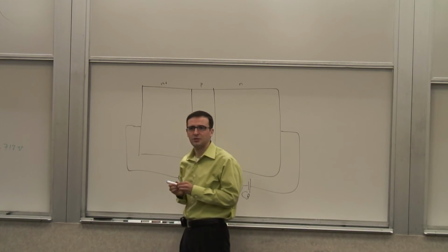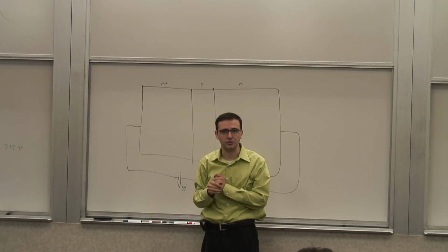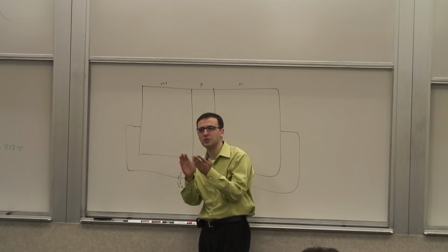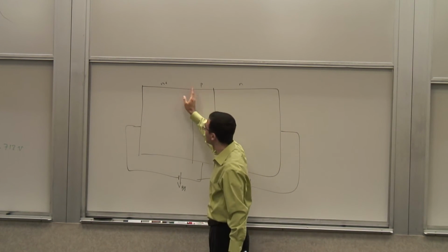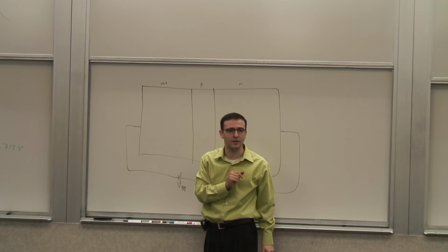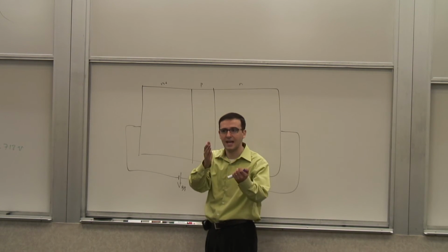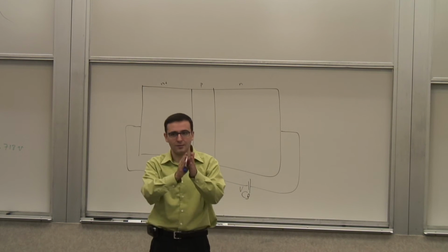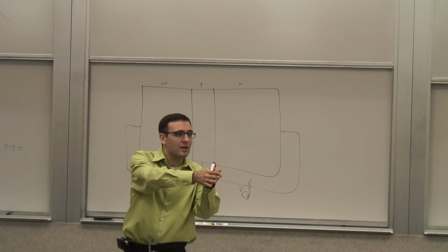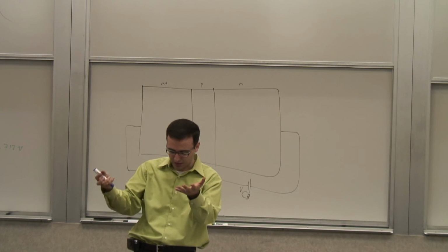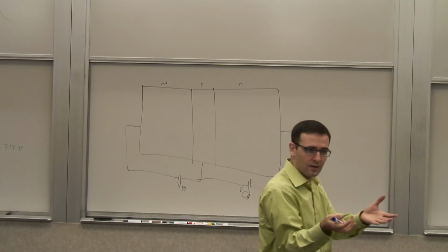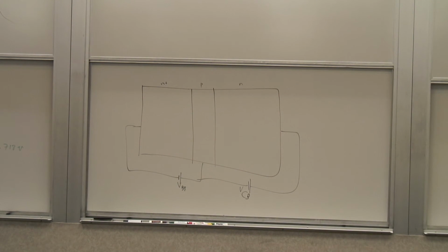And then, of course, we have the depletion region here. Now, if I were to draw a depletion region here, which side should have more depletion region? Which side gets most of the depletion region, based on what we've said so far? Would most of the depletion region fall on the emitter side or the base side? Base side. Why? Exactly, because we saw that most of the depletion region is dominated by the lightly doped side, because of the conservation of charge, right? The charge on this side and that side have to be the same, and the charge comes from the ionized dopants. So the side that has the smaller concentration of ionized dopants has to be extended farther to compensate for an extension on the other side.